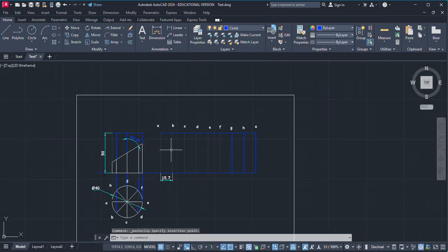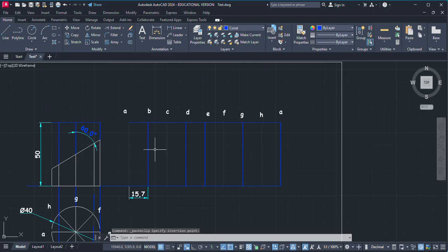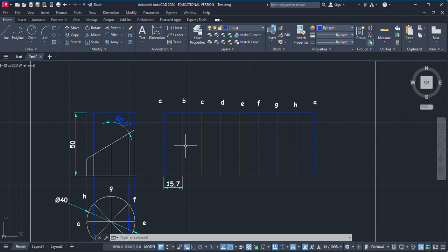And if we revolve these lateral surfaces, this will come again to this point, so this line will coincide with this one. So we will have only 8 arcs, or 8 lateral surfaces. This is the primary lateral surface of the vertical cylinder, and out of this lateral surface, we have to develop the lateral surface of this truncated body.